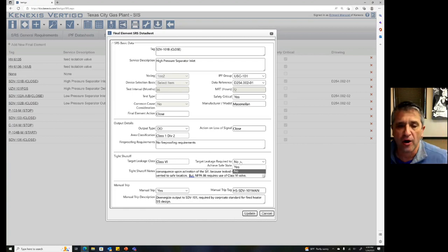And therefore, when I do my 61511 SIS validation, when I do my 61511 function testing, I'm not required to do a leak test to comply with 61511. Now, you still might need to do it to comply with NFPA 85 or NFPA 86, but we're making it clear that that leakage requirement is not part of 61511 compliance.